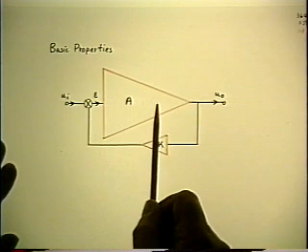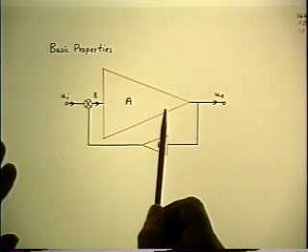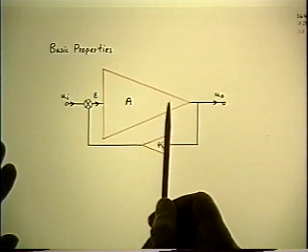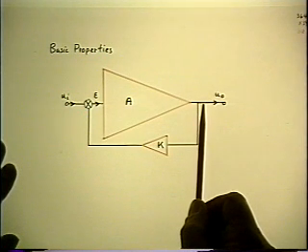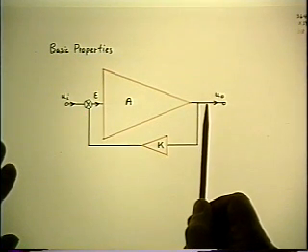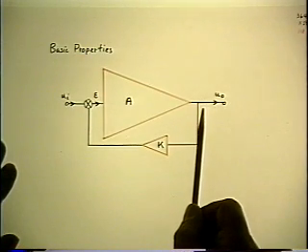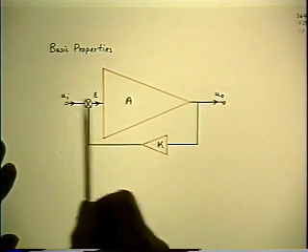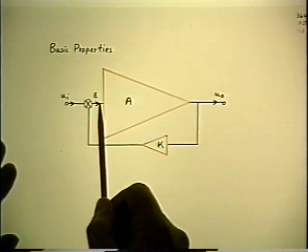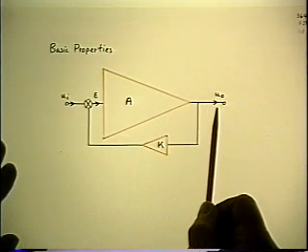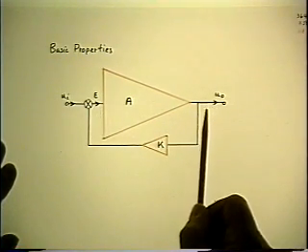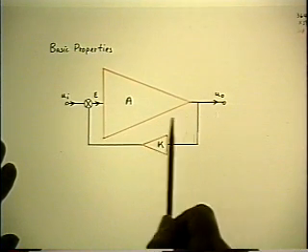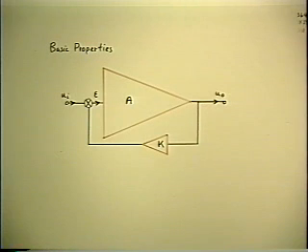So the amplifier now has an input that contains attenuated reversed phase harmonics. So it amplifies the reversed phased harmonics, so the new distortion that comes in is partially cancelled because the phase is opposite. And so in the output, you don't get the ideal perfect result of no distortion, but you get a much reduced distortion. And it's self-adjusting, because whatever is not cancelled out gets to be fed back and re-amplified. It's the reversal of phase that causes the partial cancellation. So he had to iterate the solution to his problem to get the answer that finally worked.